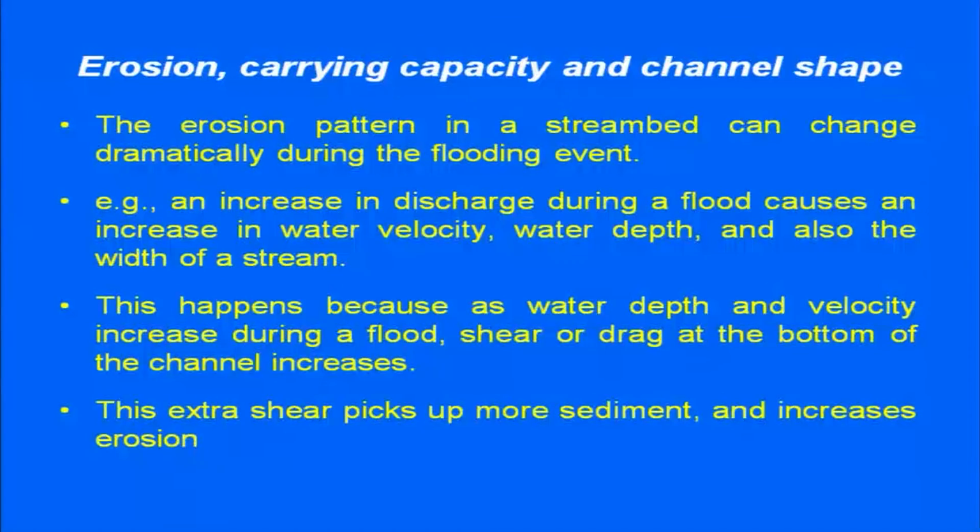So, quickly, if you look at this: increase in discharge during flood, so higher precipitation, increase in water velocity, water depth and width of the stream. Drag will increase during the flooding state, and this drag will pick up more sediments and will result in erosion.